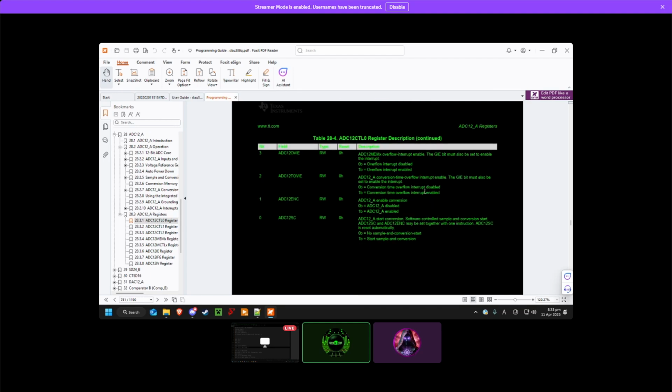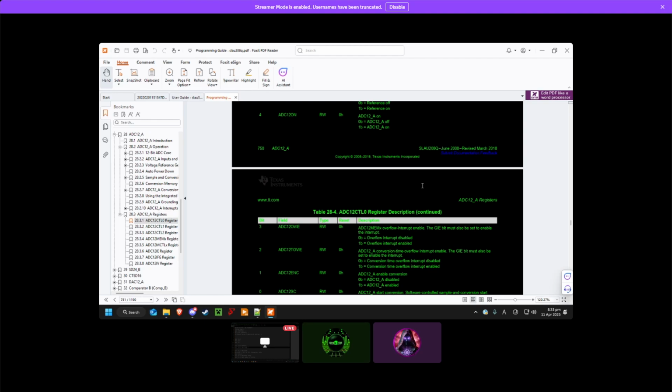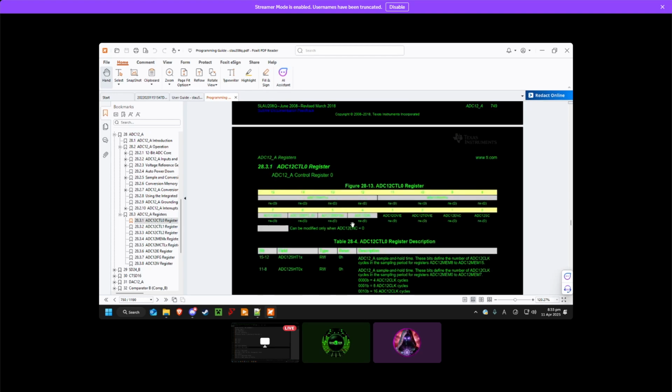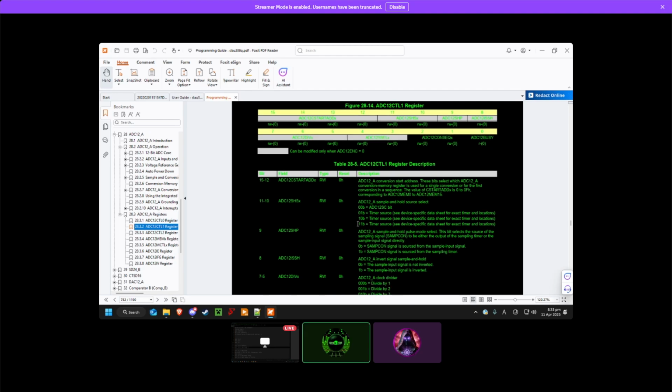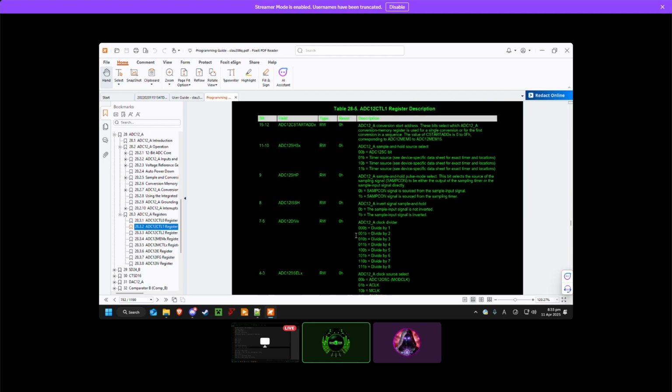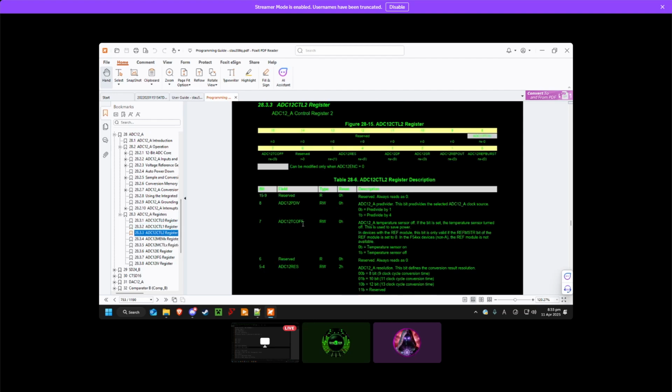So all of these are important to review, and we'll do that in the next one when I am better prepared to review this. But this is the first option for the ADC12. You have another option that this needs to be configured. This gives it timer sources and clock dividers. So essentially, you set up the ADC12 clock. There is another one. This is where you can change the resolution for it.